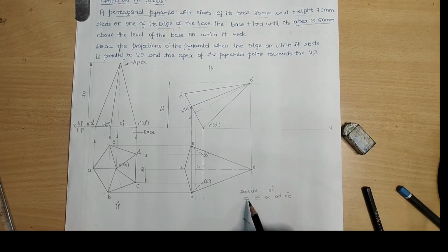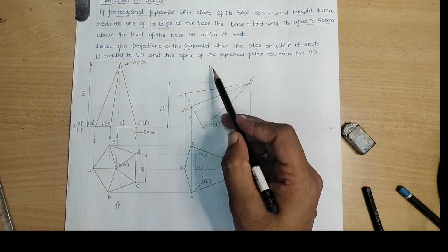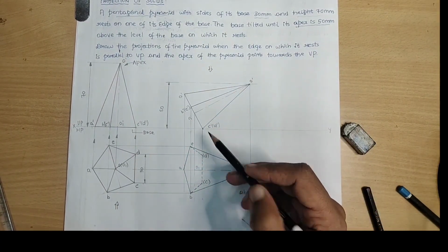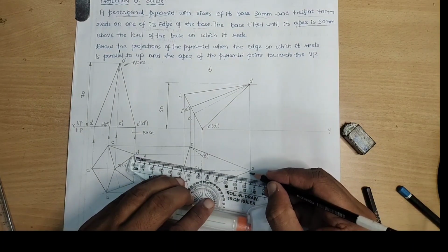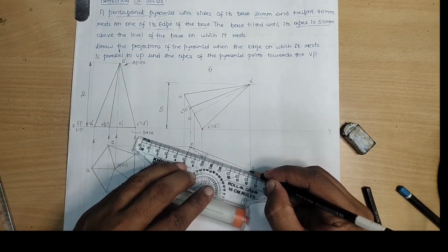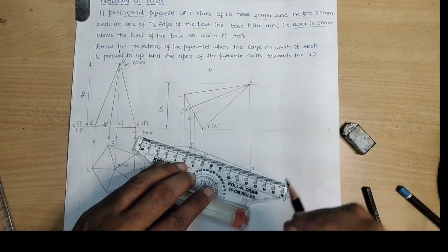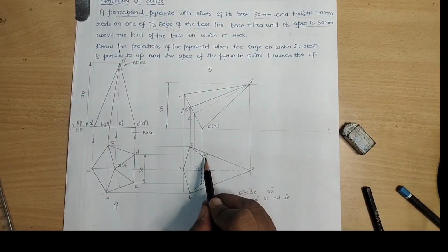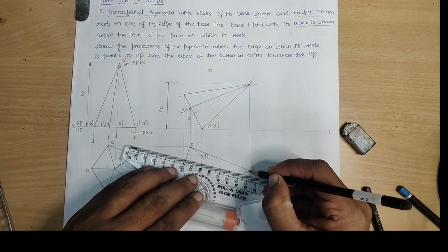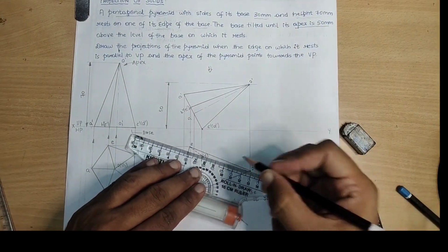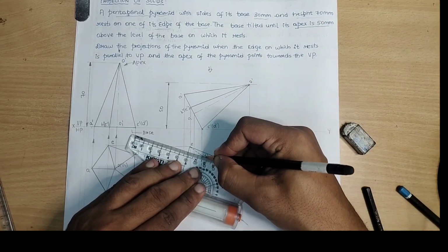Next, let us analyze what is the condition of O to C and O to D. Observer is looking from the top. C and D form the farthest point from the observer. Henceforth, O to D is invisible. Or in other words, don't you think this is the invisible corner? If you draw a line from the invisible corner, that should be invisible. Henceforth, O to D is invisible.